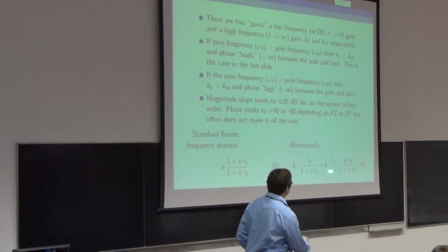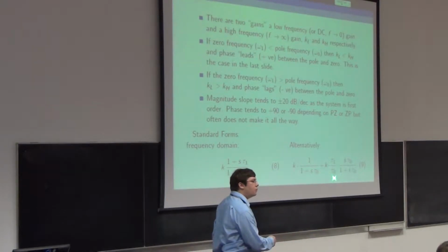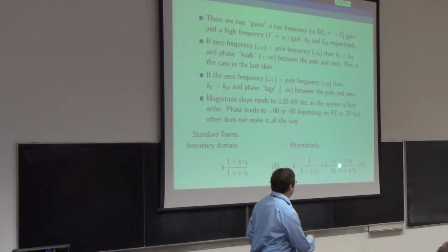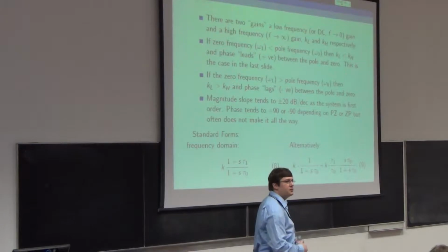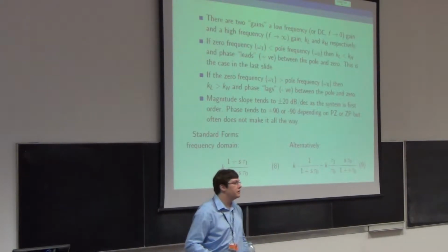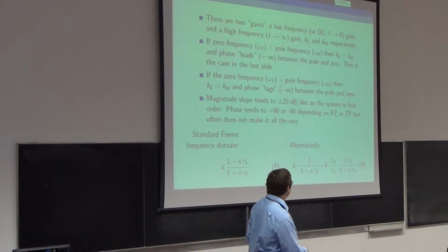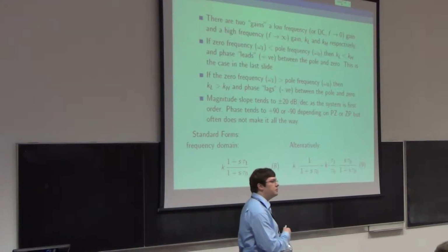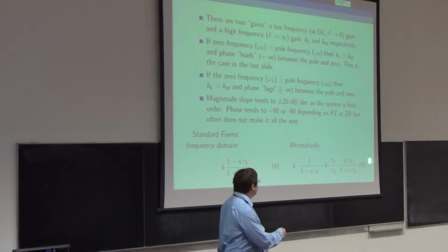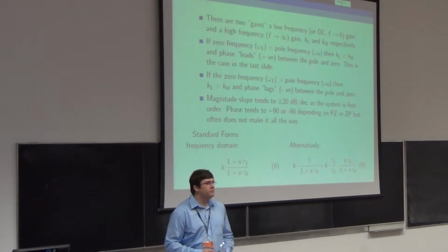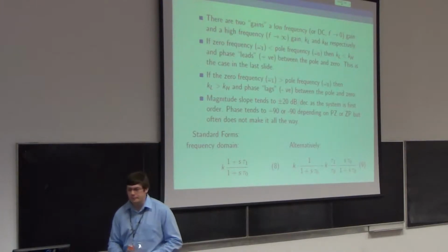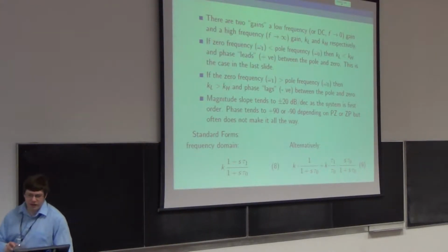So all of your frequency dependent stuff is now to do with the pole time constant, or the pole frequency, and you have a converting factor in the middle, which deals with the fact that the 0 and the pole aren't at the same frequency or don't have the same time constant. This is quite useful because if you want to know what happens to the high pass and low pass bits without having to think about where the 0 is, you can do it from this bit. It can also make it easier to see what the rise time is going to be like, if you prefer. Sometimes you'll see it drawn either way.